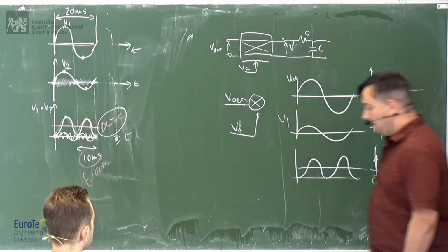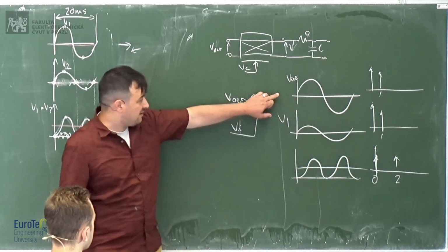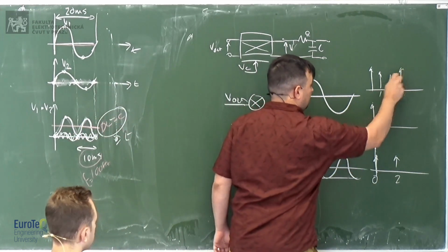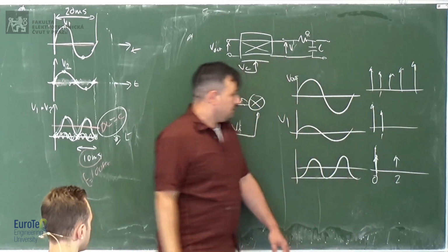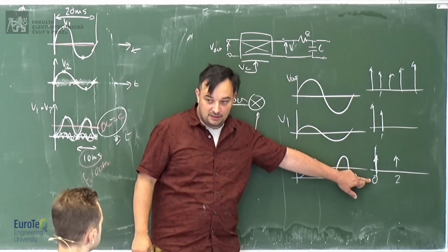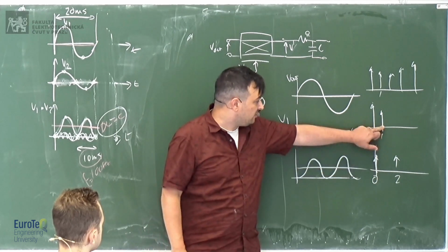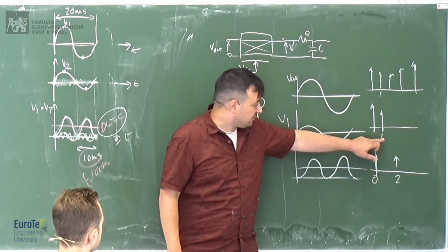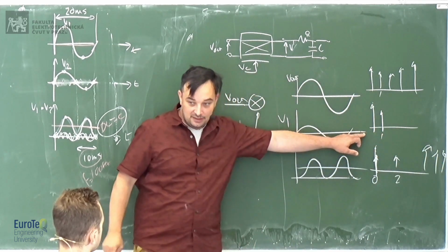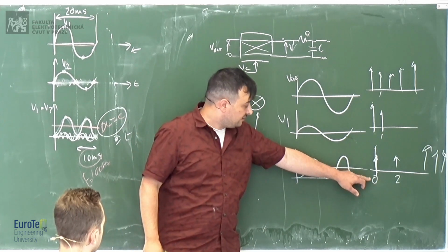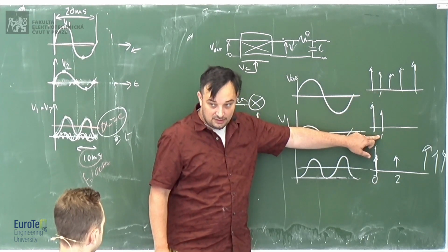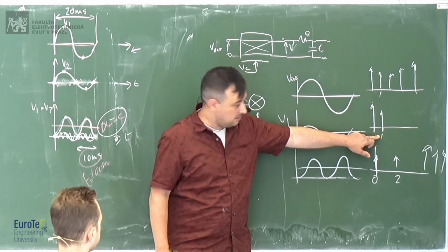Now, in this case, if the signal contains some bad frequency, some disturbance whatsoever, you don't have any problem because they will never end up at zero, okay? They will be multiplied, and the output will contain frequencies which will be here, here, here, here, according to the sum and difference with 1, but they will never be at 0 because the only case you have something at 0 is when you have 1 minus 1, okay? Is this clear? Okay.